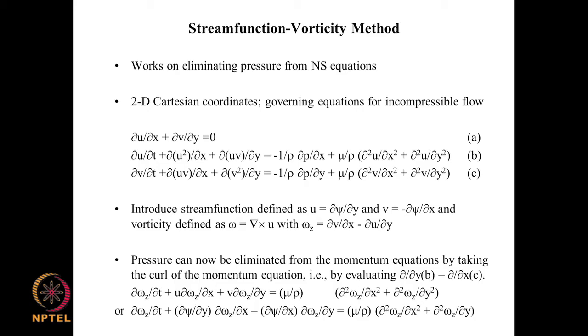There is a different philosophy in the stream function vorticity method. The idea here is that since pressure is a nuisance variable, can we eliminate pressure from the Navier-Stokes equations?